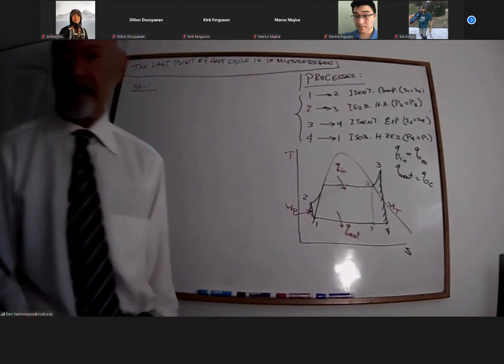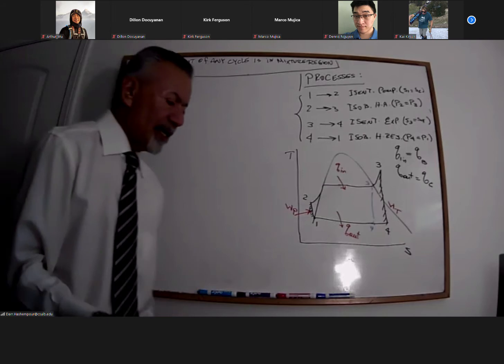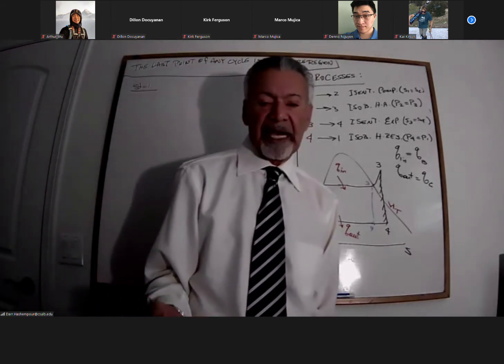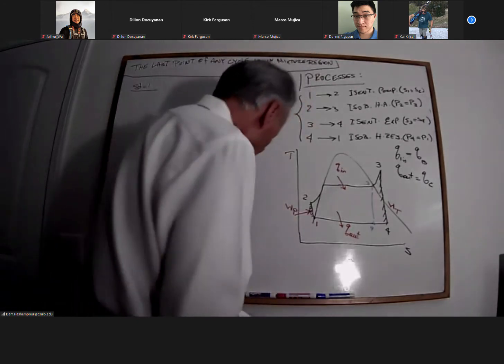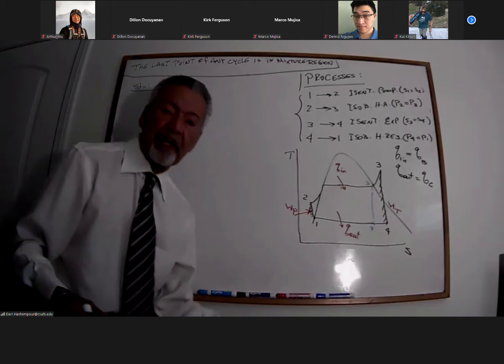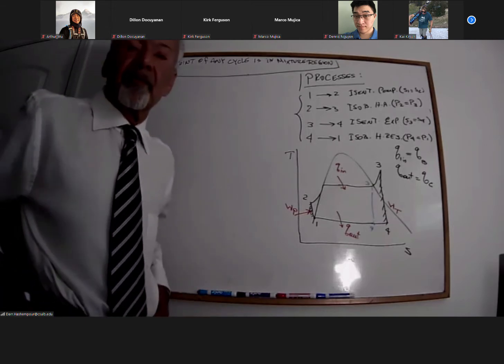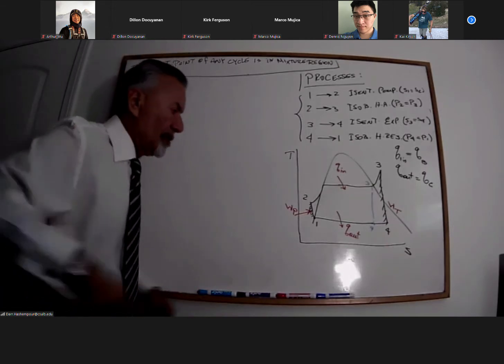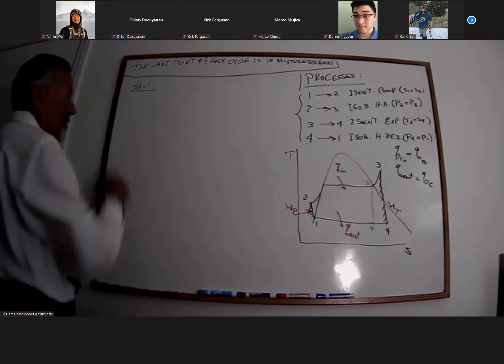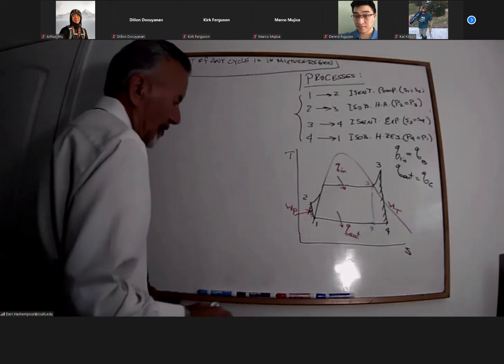We don't have to convert it, because the reason we converted in chapter 9 was that we were dealing with ideal gas equations. Here, we don't have an ideal gas equation. So we don't have to worry about converting it to degrees Kelvin or Rankine. So at state 1, I need to have 2 points of reference.